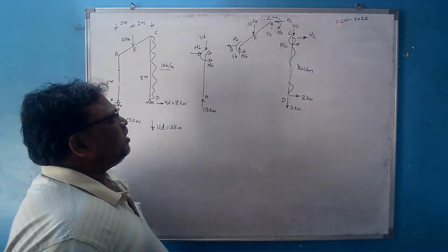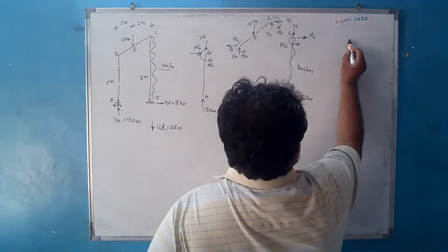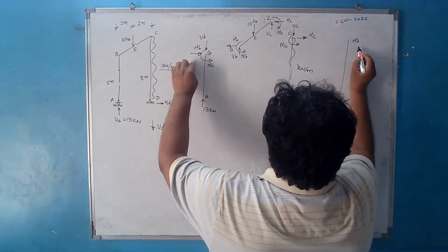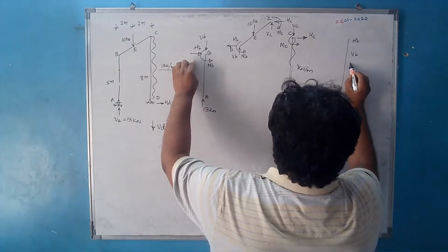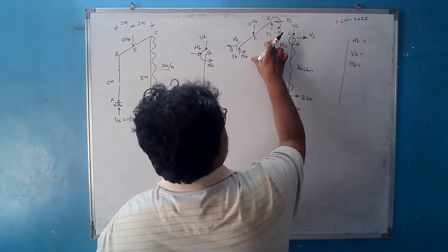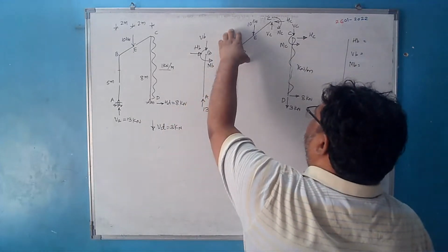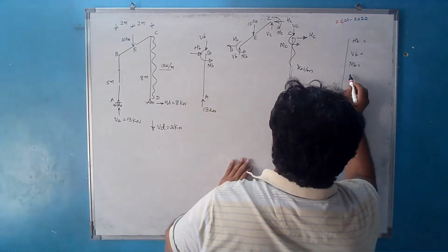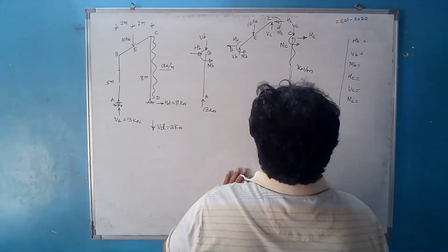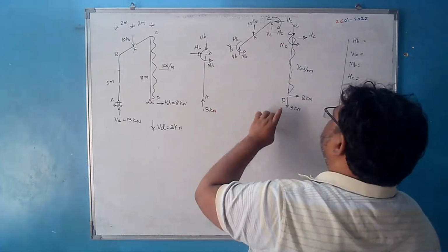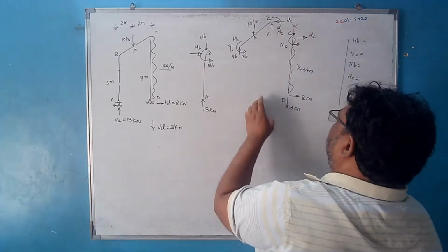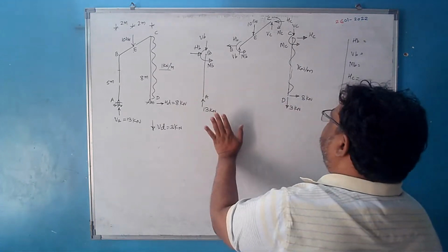Now if you see what the unknowns are here, I will make a list of the unknowns. The unknowns are HB, VB, and MB. These are the 3 unknowns. If I see this member, these 3 unknowns are already counted. The other 3 unknowns are HC, VC, and MC. If I come to this member, these are the 3 unknowns, but they are already considered here, and that's finished. Here all the other forces are known.